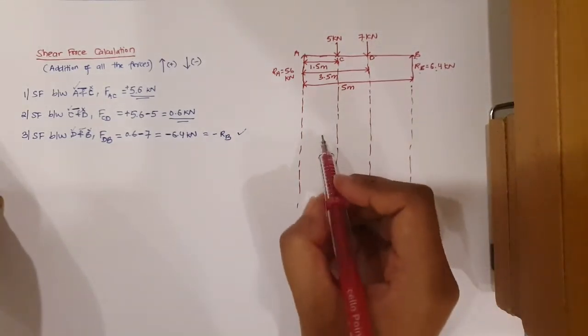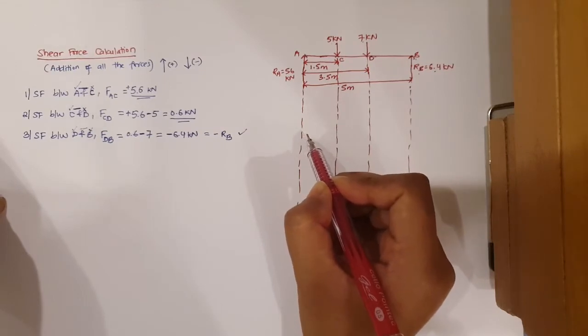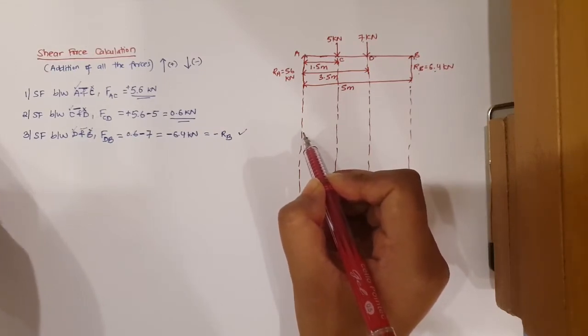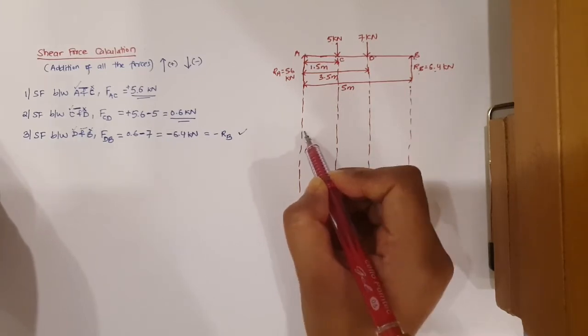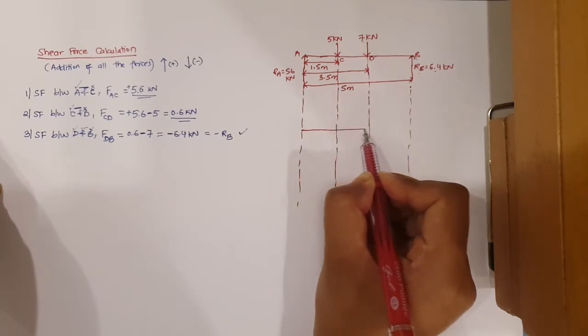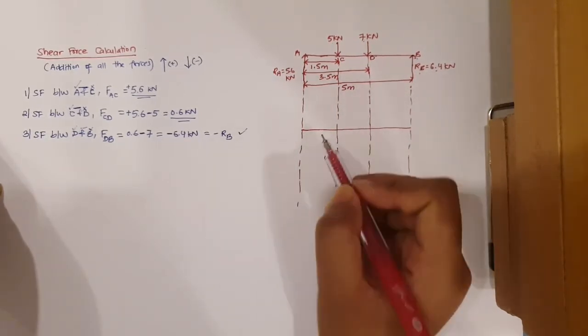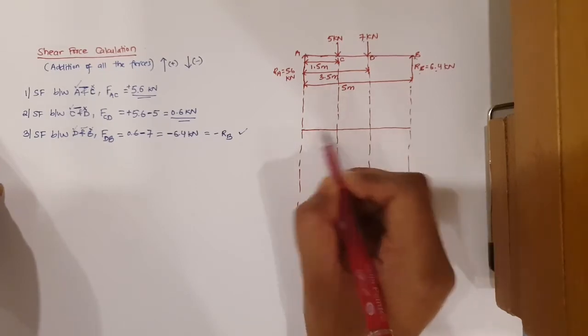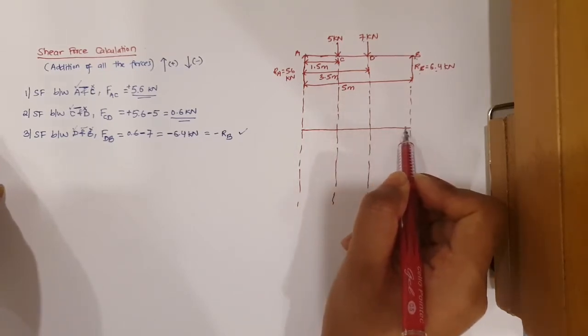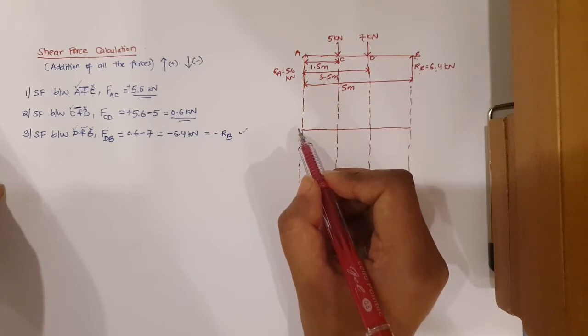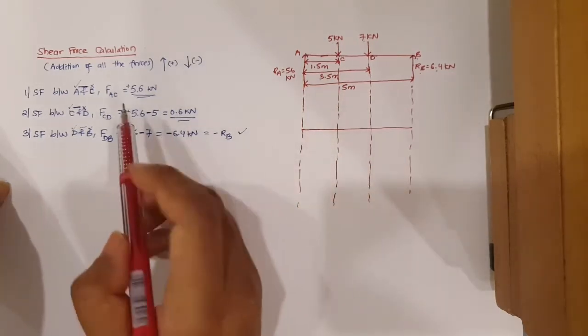Okay, now to draw a shear force diagram there are certain rules, so I'm gonna show you those certain rules. So this is the line. Okay, above this line let us first mark the forces that has come in between.